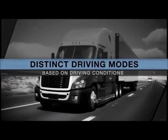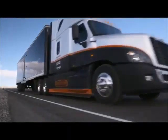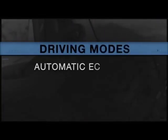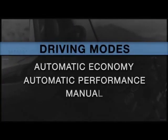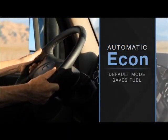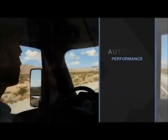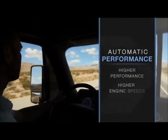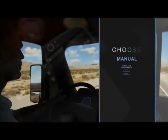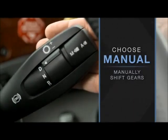Distinct driving modes let you choose the mode that works best for your current driving conditions. There are 3 driving modes: automatic economy, automatic performance, and manual. Automatic economy mode is the default and, along with intelligent gear shifting, is designed to save fuel. In automatic performance mode, gear shifts are designed for higher performance and are made at higher engine speeds. In manual mode, gear shifts are requested manually.